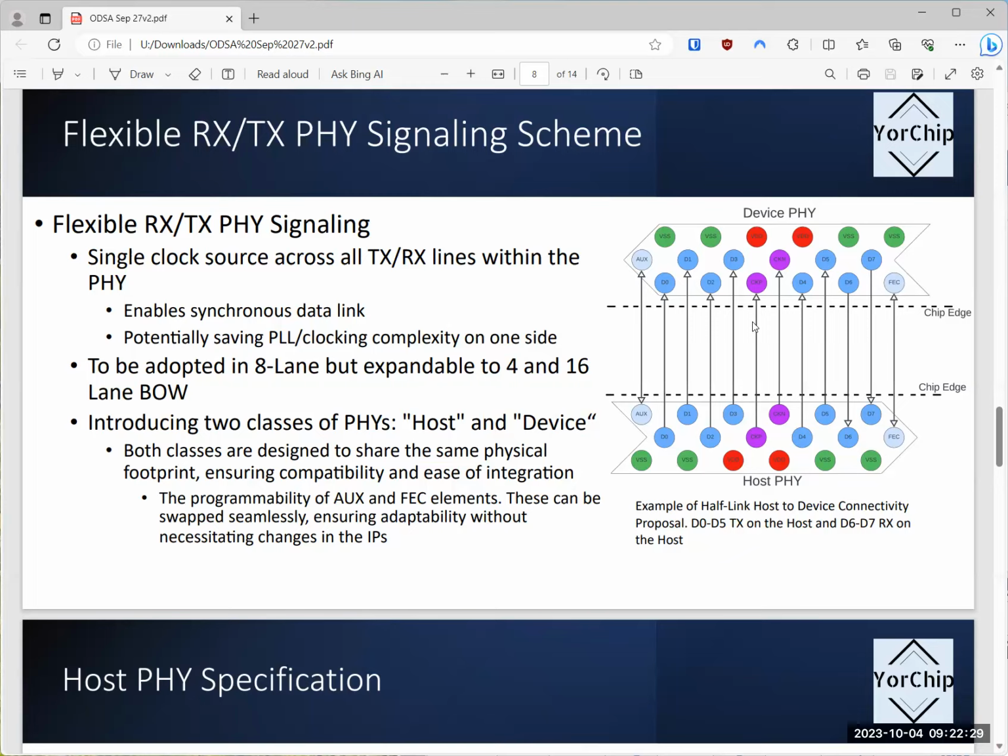Okay, so we can make it work on the half cycle shift and disable the half cycle shift. We can work on disabling it in logic as well, but to support two modes, my timing constraints have to assume it can work both ways, meaning there's an additional timing sign-off check that I need to consider for both scenario usages.